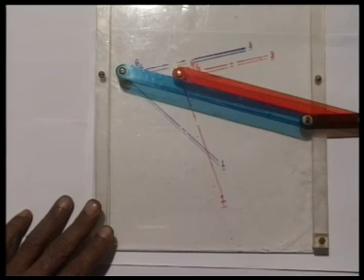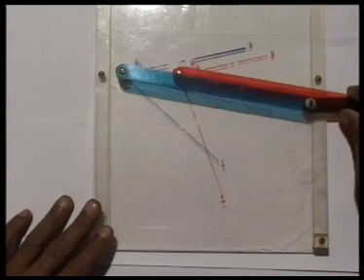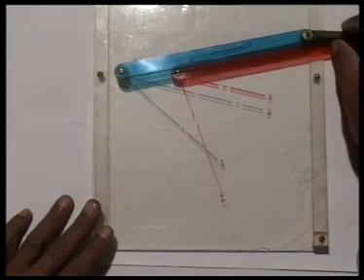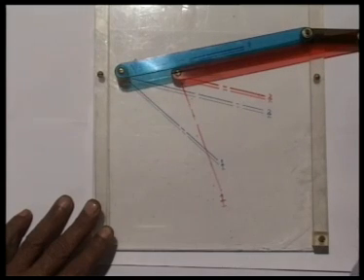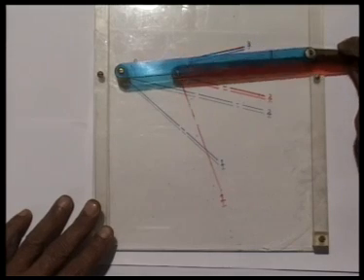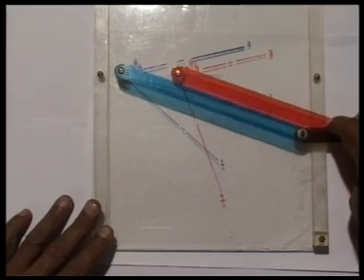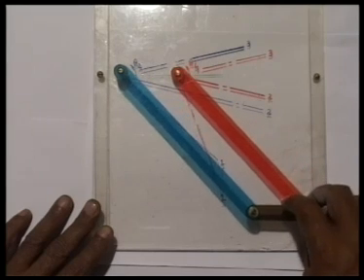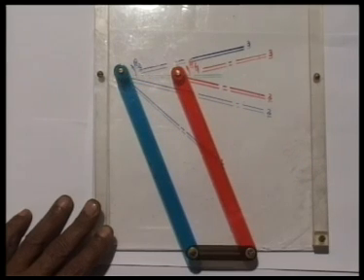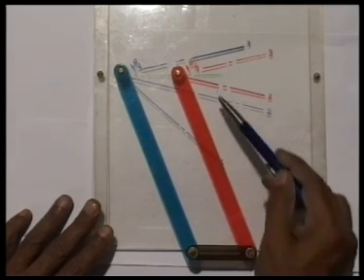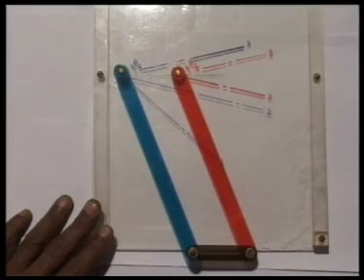If we now change it to the parallelogram assembly, then we see the second configuration is satisfied by the mechanism. Same way, if we go to the third configuration, it is only the parallelogram configuration that will take the third configuration, but if it gets into anti-parallelogram configuration, then the first configuration is not satisfied for obvious reasons, because theta 2 and theta 4 are not equal.